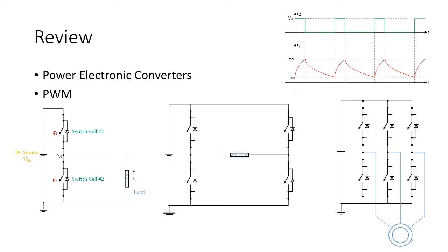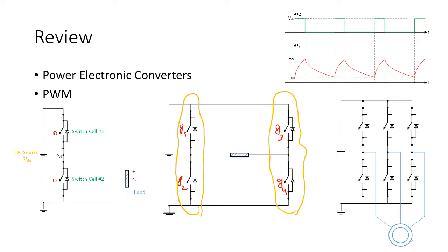What we said is that the full bridge is very similar to the half bridge. It's two half bridges, in fact; we can treat it as two half bridges, one here and one here. We have VA, we have VB, and VL, the load voltage, was equal to VA minus VB. So VL average was equal to VA average minus VB average.